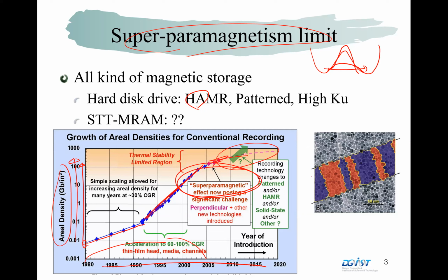This kind of approach can be applied to any kind of storage media, but giving additional heat requires more energy and it's usually slower dynamics. So this is not a very ideal approach, but nowadays the hard disk drive industry is trying to make this heat-assisted technology, otherwise we cannot overcome the limitation. In STT-MRAM also, such a kind of problem is very important, so we're going to talk about that.